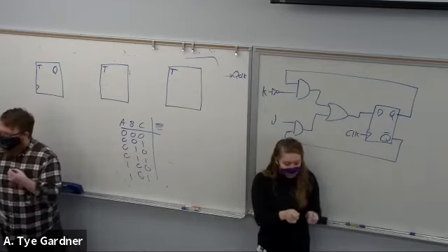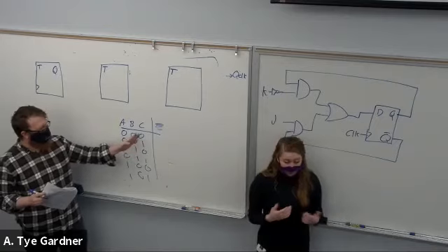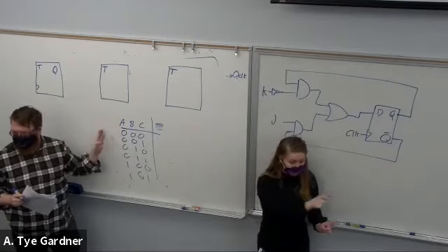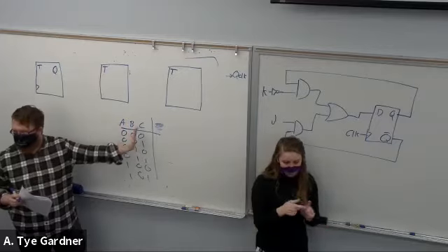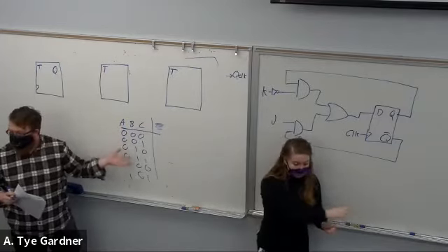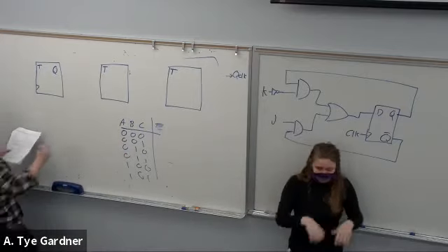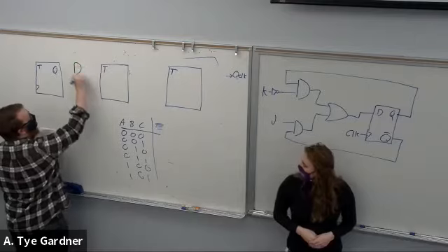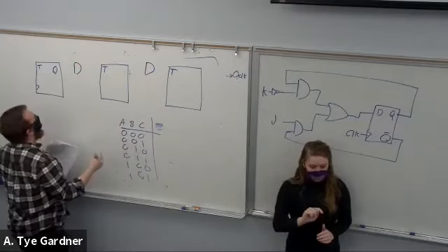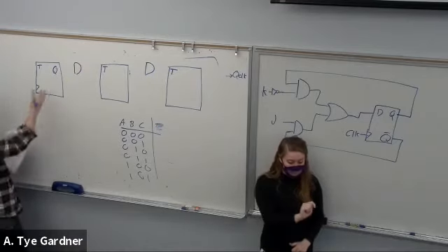So if we think back to our clock divider, right? And as long as we're toggling each larger bit column at half the speed of its lesser bit, then we can just count. We build a counter. Okay, so how do we do that? Well, we're toggling, meaning we're flipping bits. So we just want to set up a T flip-flop. That's our easiest one to draw.